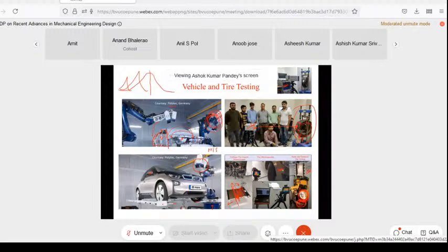All this happens when we drive at a high speed. You have a temperature rise, and with wear and tear of the tire, to an extent that you can't really control its rupture, and this is where the tire burst phenomenon happens. So we need to track the condition of the tire live, and there are many tire companies coming up with smart tires where they can provide information on the contact, on the tire thickness, and, anyway, pressure is already there, that is a tire pressure measurement unit that has existed for quite some time, but they are inserting strain sensors in the tires so that they can know how much stress is being generated in the tire.